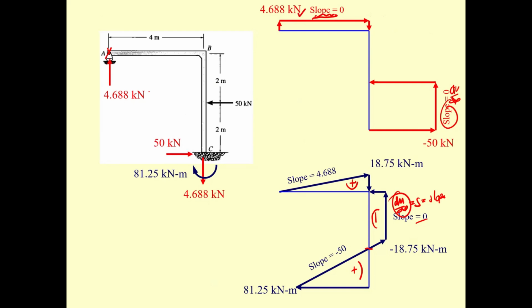Based upon this one, okay, roller. Since this is a roller and is subjected to the force over here, for sure this one is going to move to this location, and you will say this is delta sub Dy, and then the term over here is going to be delta sub Dx. No axial deformation, so this one equals delta sub Ax. Now, that is the inflection point over here, just below the loading point.